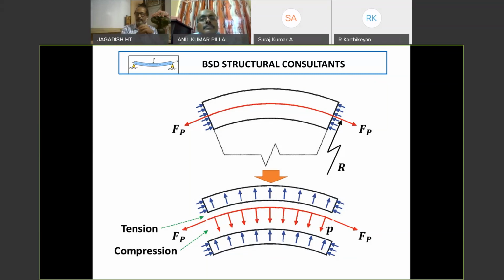Coming to the dome, what change has been done? The pre-stressing cable spacing was changed. Earlier, we used to have cable spacing as close as 100 to 120 millimeters. Then in the re-engineered dome, the minimum spacing was 225 millimeter, and that 225 millimeter was kept near the openings only. Close band of cables near the opening only, to take care of stress concentration. Balance portion area was 450 millimeter spacing. So we got more space for pouring concrete.